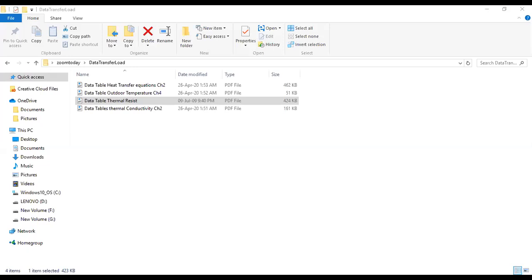And for strong windows, thick glass walls are used in the outer wall of the building, and there is 25 to 100 mm airspace between two walls. This acts as an insulation in winter and summer. So you know summer and winter values of overall heat transfer coefficient. No need of calculating thermal resistance. U is given directly. This U will not be added in thermal resistances.